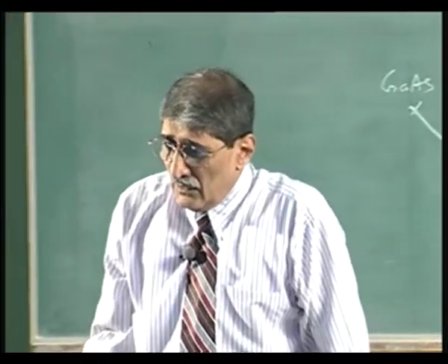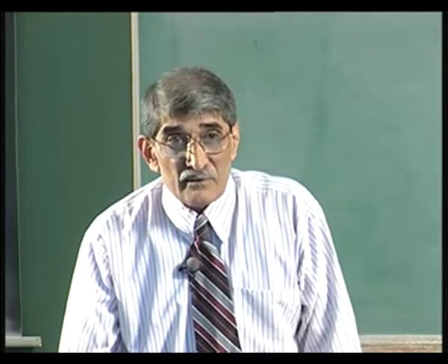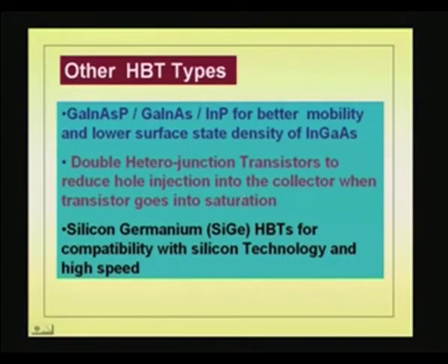So, that is why I just thought I will point this out to you, because this is something people have been exploring. But if you are working on an emitter coupled logic circuit, you do not have to worry about that, because there is no forward bias on the collector base junction, there is no saturation, it is only active. Still, you can make use of this without using ECL, for high speed devices. So, you can see that bipolar HBT is a potential candidate for high speed devices.